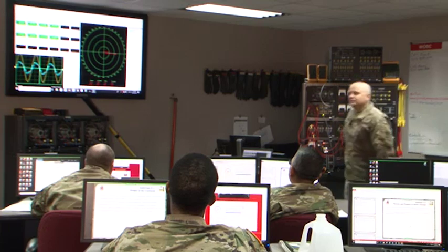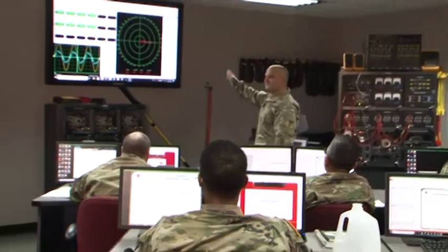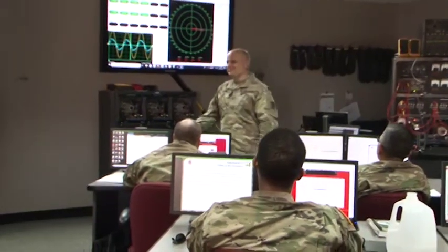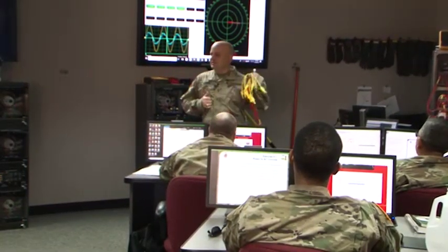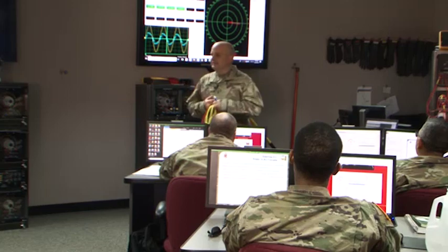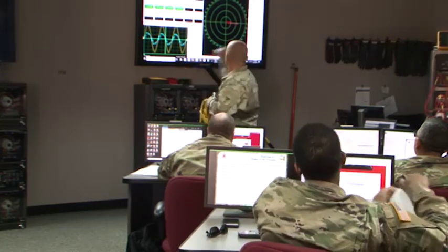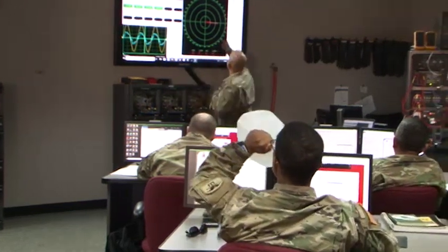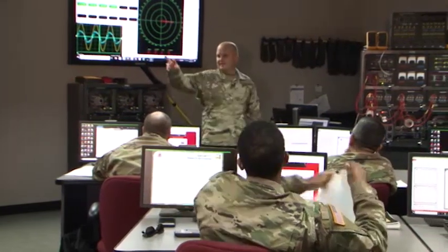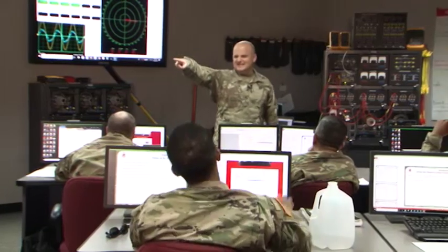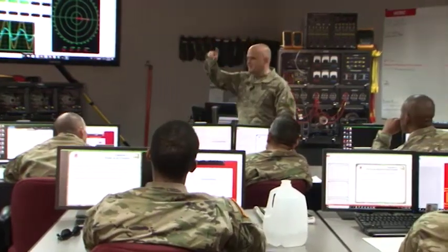All right, so now we're not perfectly at 0. Why are we not perfectly at 0? I got the same amount of capacitance as I do inductance when it comes to reactance. Well, resistance is pulling this way. What is that little bit offset? It's like the impedance in all the wires and stuff. The resistance in the inductance is creating a little bit of active power there.